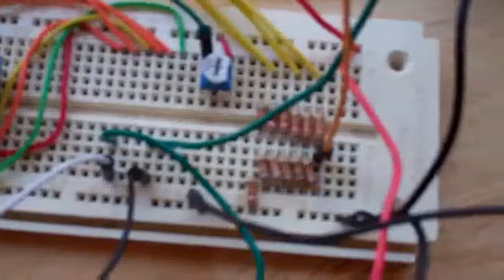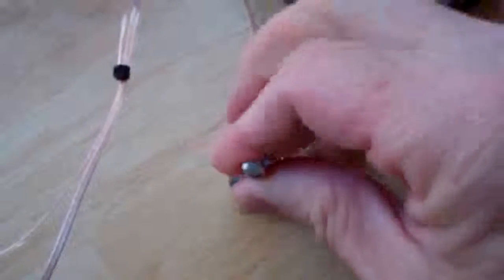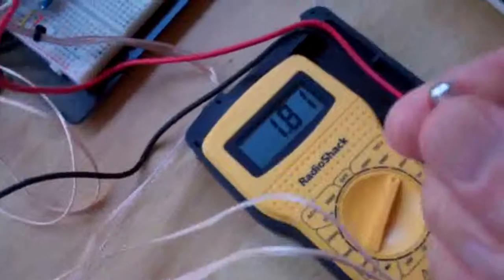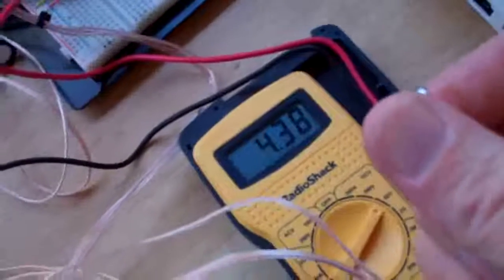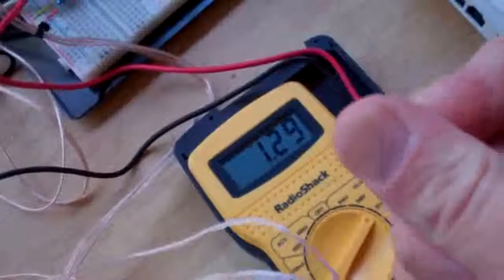So we have the single output, which is coming on 6 digital lines because we transmit it as digital information. It goes through a simple 1-2 resistor ladder to give you a 6-bit D to A, which comes out on this orange line and goes into a voltmeter, grounded out. And now we can set one potentiometer all the way up to 5 volts, and this other potentiometer can be turned, and as we turn it, the voltage goes from 4.38 volts, that's as high as the D to A goes, all the way down to 0, and anywhere in between.